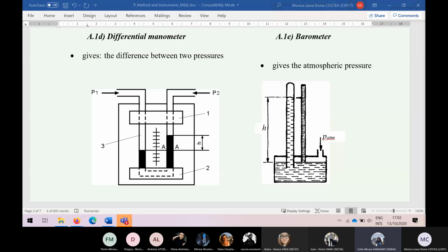Yes, it's relative pressure. Okay, so the conclusion is that all of you will make a huge mistake in further calculations. First of all, in order to use the atmospheric pressure in an absolute pressure calculation, you have to know the relative pressure. What is it? Manometric or vacuumetric? Otherwise, you cannot use that formula. Here, you have no information. It's just a pressure difference.